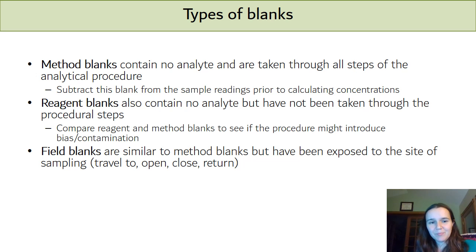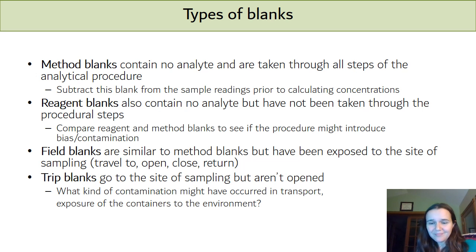So you take this blank, it's a reagent blank to start, you take it to the site where you're sampling, you open the bottle, you close the bottle, you bring it back, and then you put it through the whole procedure. And that's really testing to see if there's something at the sampling site that has contaminated your material.